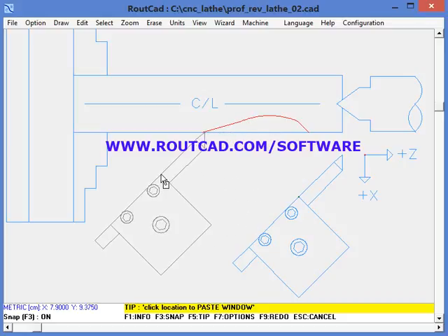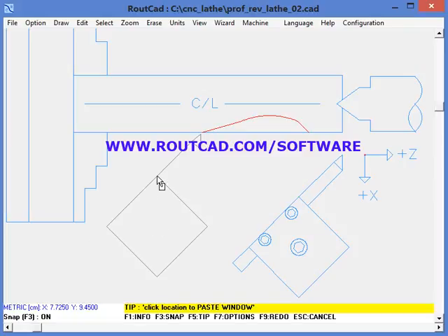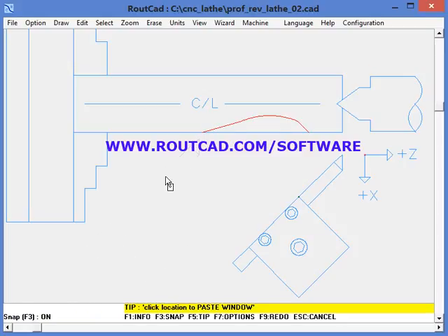It is good to make a kind of simulation of how the profile will be, so that we make sure, for example, that our cutting tool will not hit the chuck, or we also make sure that the cutting tool, when it's going through the profile of revolution, is able to go nicely in the material, and it will be able to make that profile of revolution.